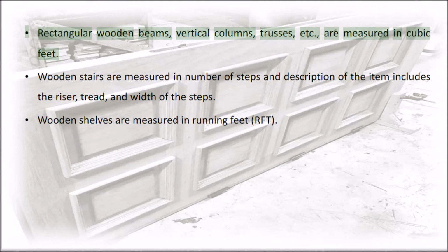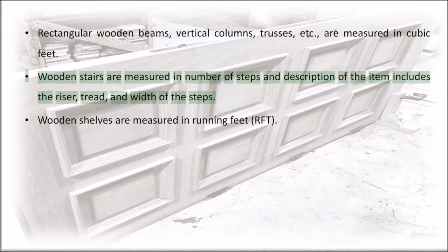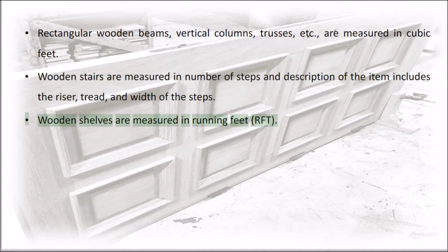Rectangular wooden beams, vertical columns, trusses, etc., are measured in cubic feet. Wooden stairs are measured in number of steps and description of the item includes the riser, tread, and width of the steps. Wooden shelves are measured in running feet, RFT.